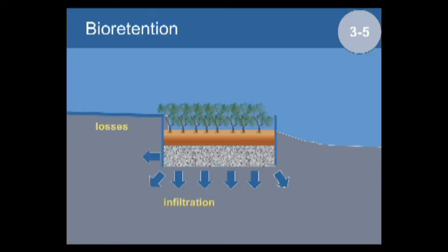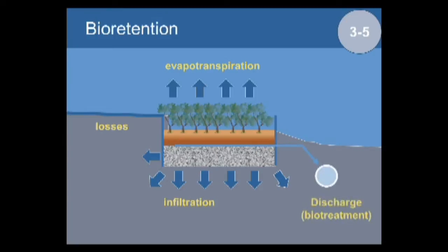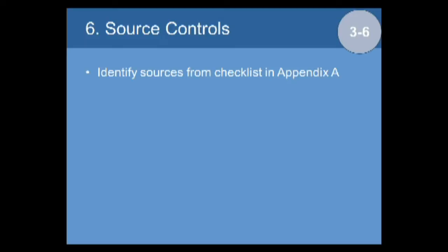And again, the reason we like these, and why we moved in this direction from all the other landscape-based forms, is these capture the runoff. You can put a lot of area into them. They pond it, they filter it through a porous medium, and they promote infiltration into the soil below. So you get the combination of the treatment and the retention and infiltration. And then where you don't have the capacity to infiltrate, you get treatment before discharge.